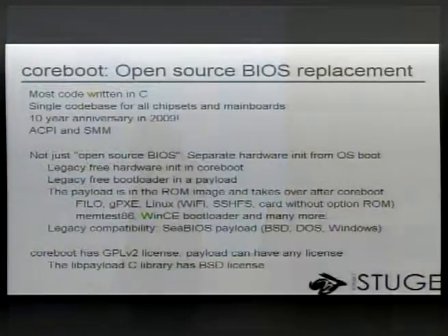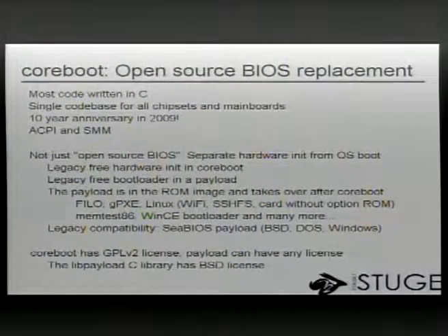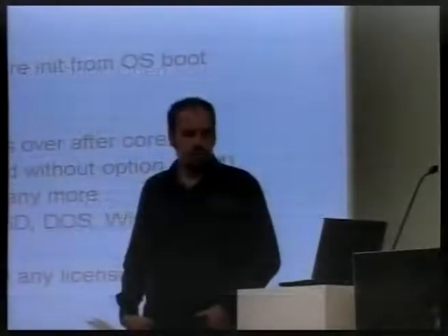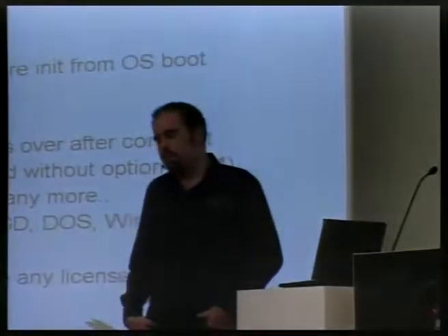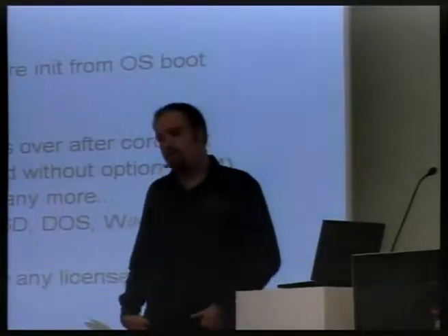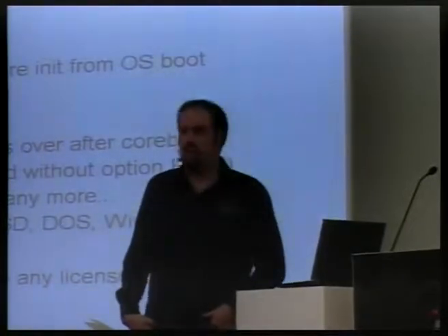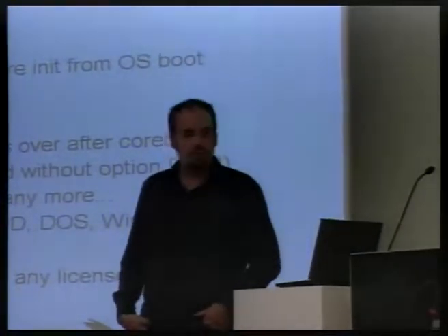Coreboot is an open source BIOS replacement. It's written mostly in C, as opposed to many of the commercial BIOS sources, which are a lot of assembly code. It's one single code base, supporting all the chipsets and manufacturers and mainboards. Sorry, no, not vendors. 200 components and 200 mainboards from, I guess, maybe 50 or so vendors.